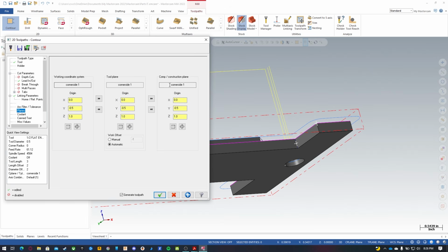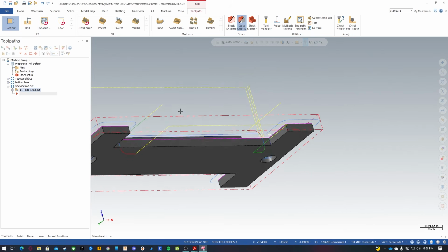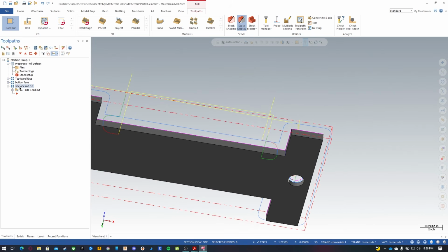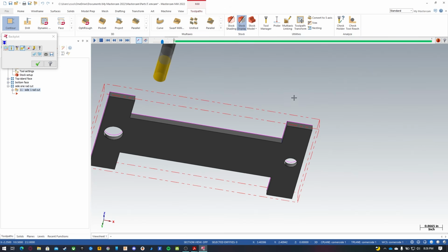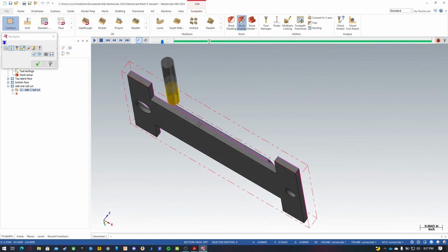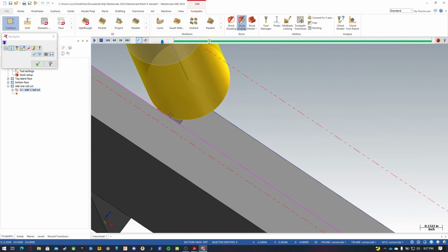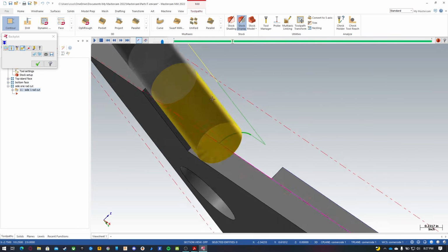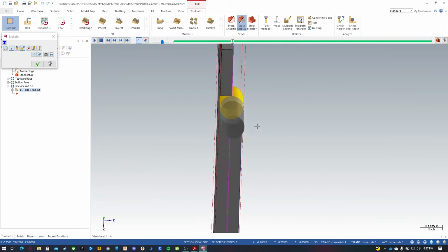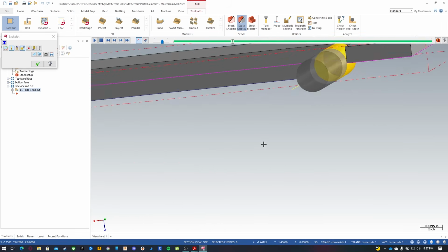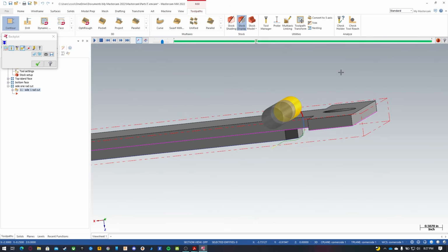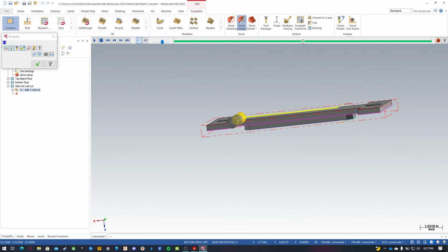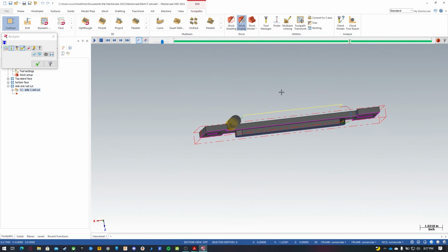So if I go to my planes, corner side is all selected. I just want to make sure that my toolpath is going to be safe. So it's going to come down. It's going to start just outside our edge. And we can always make that extended a little bit. And it's going to feed in. And it's going to skim that edge and wrap it over and do the same thing to this guy.